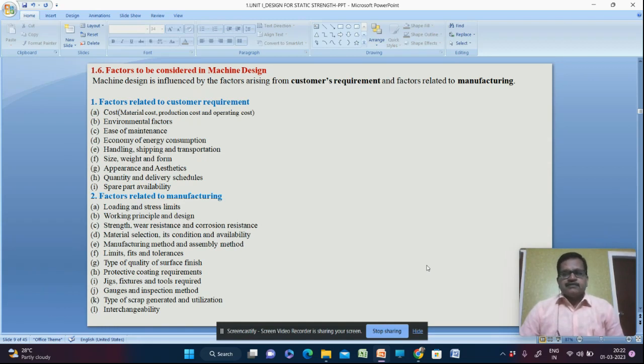One of the reasons is, let us say, if a shaft has to be made with 50 diameter, the shaft is placed in bearings. That means the inner diameter of the bearing should be greater than this 50, and several things like gear wheels or flywheel or pulleys are mounted on the shaft whose internal diameter should be greater than the diameter of the shaft.